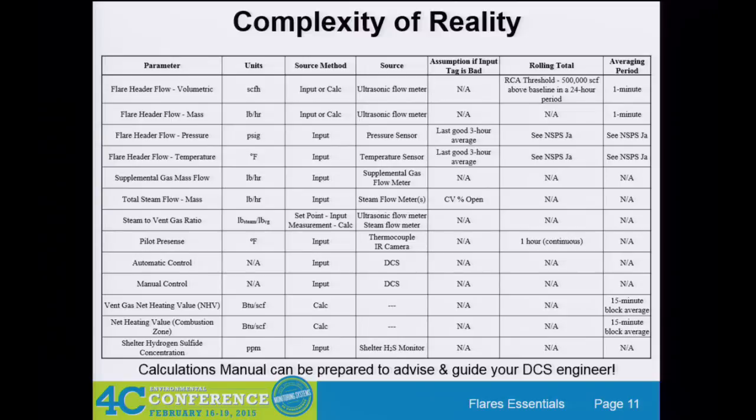That's a case-by-case situation, because a lot of times with some of these meters, they're not just working fine and then all of a sudden don't work. They'll drag down over time, with a slow decline in the response factor, and suddenly you don't know how long you've been out. It's not like I've been at this one reading for a month and I know it should be that. Over the last month, you could have been slowly declining, so you don't really know where to put that value. That's something you would have to build the rationale around.